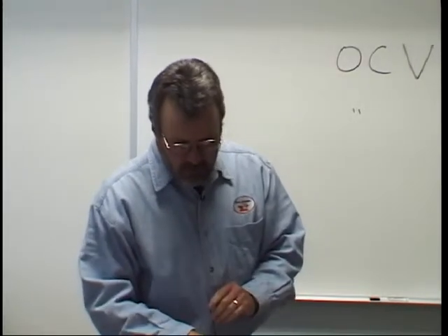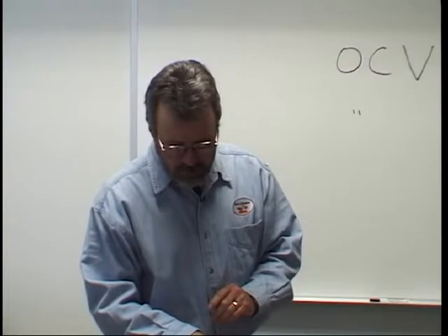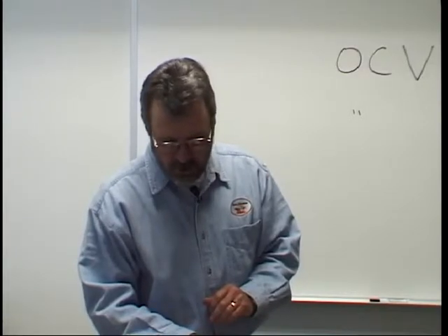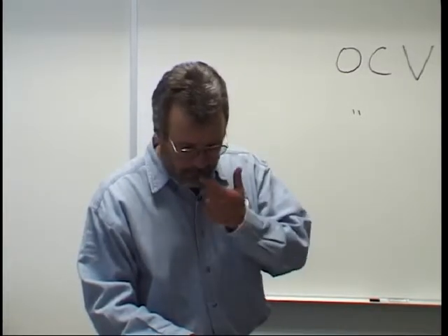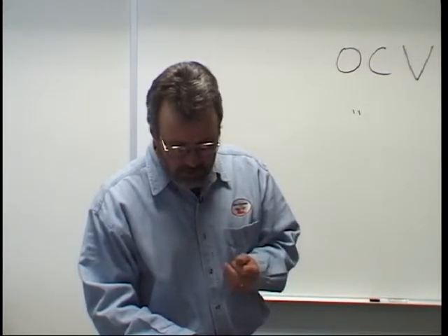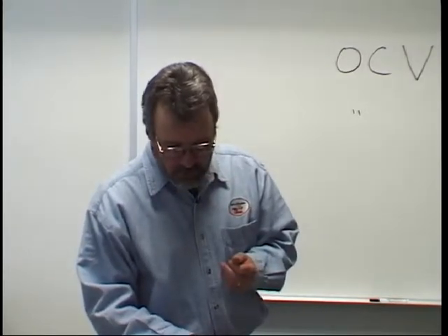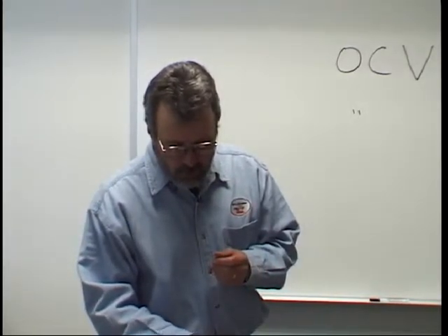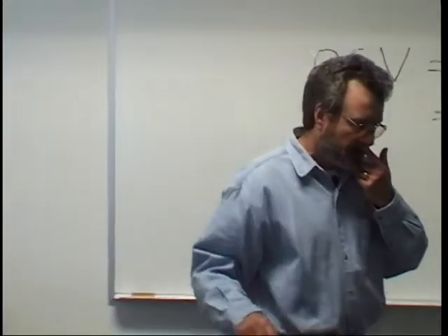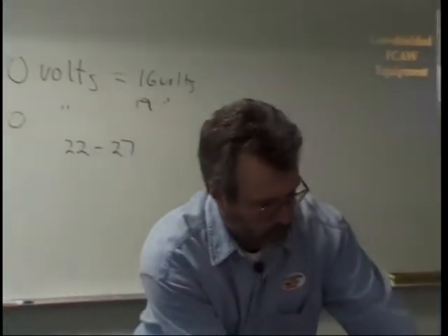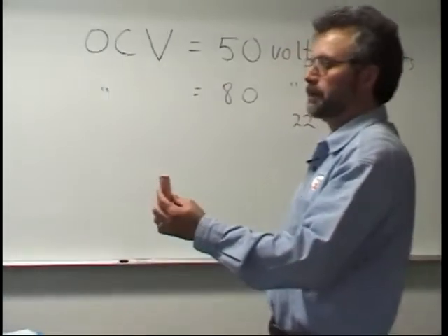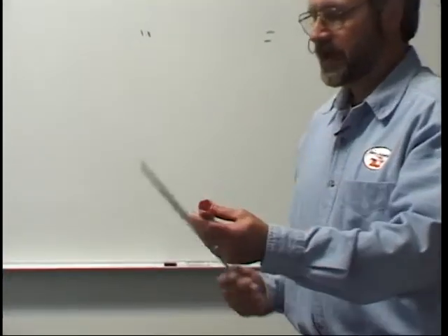Under nozzles, many different types of materials are used for nozzles. You can get them in copper and copper alloys. A clean, smooth nozzle will allow easy removal of weld spatter. The welder should not roughen up or abuse the gas nozzle on the gun. This one that I showed you that we use for spot welding is just one example.